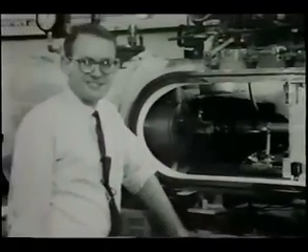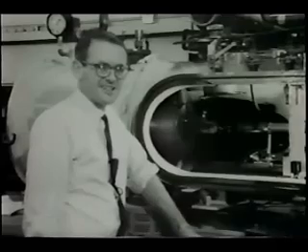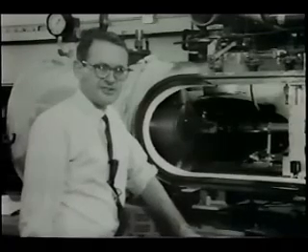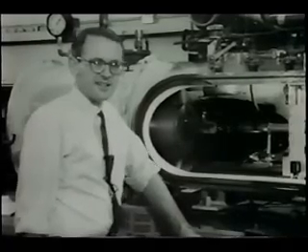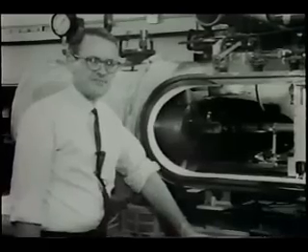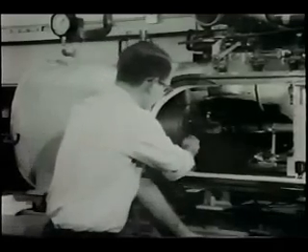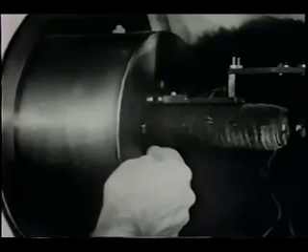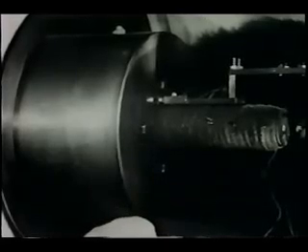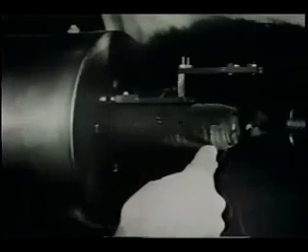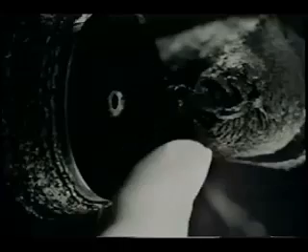The pictures we just saw were taken in this little wind tunnel, again using the sodium vapor flow visualization technique. A nearly constant flow of sodium is generated in the boiler here and mixed with a controllable flow rate of argon. The mixture then discharges through this converging nozzle and into the test chamber. The re-entry body of our picture is this little washer. It's electrically heated so that the sodium won't condense and collect on it.